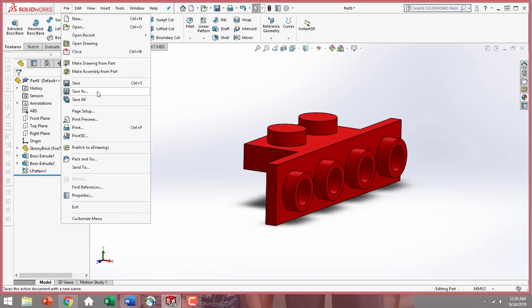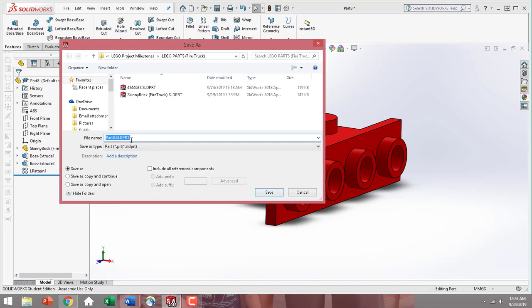So go ahead and hit File, Save As. Make sure you're saving in the right area. This is really important because when you start creating your assemblies in your main assembly, if you're not pulling parts from the same file every time, it's going to get lost when you go to submit it. Your instructor won't be able to pull the right files and your assembly won't work. So you want to always save everything in the right folders in the same area, and you're constantly pulling from the same parts. So this is part number 4282742. Then hit OK.